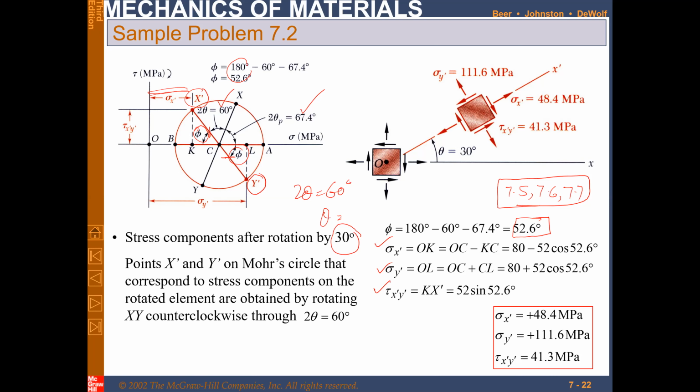Now what we have done till today is that we have different sorts of loading conditions. We know their expressions. We know where these are the maximum and where these are the minimum, on the basis of which we can calculate the current state of stress, that is sigma x, sigma y, and sigma z, and then ultimately use those conditions to draw the Mohr's circle, and from Mohr's circle you will calculate the sigma max and sigma min and tau maximum and tau minimum values, and the angles at which your principal normal stresses will be occurring, right? And then you can decide that if your allowable stresses are greater than sigma max and tau max values, you are safe, otherwise you are not.